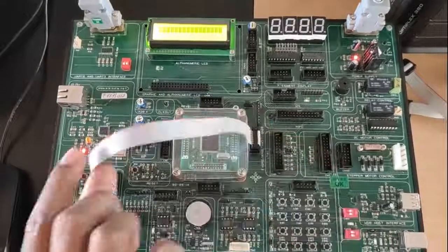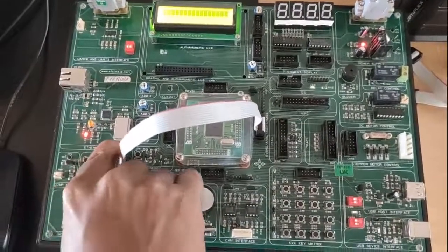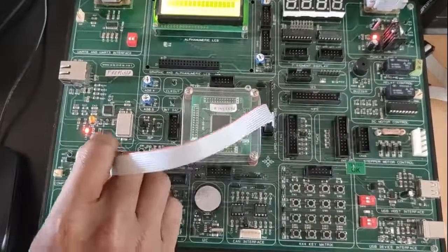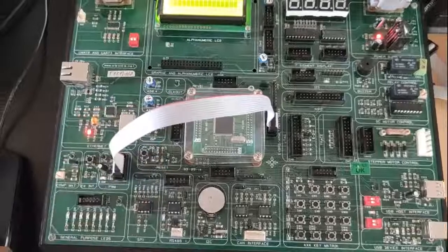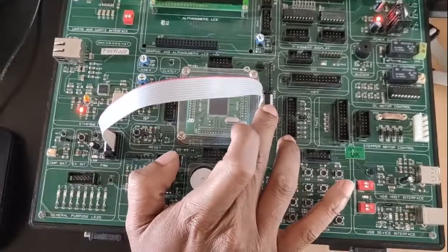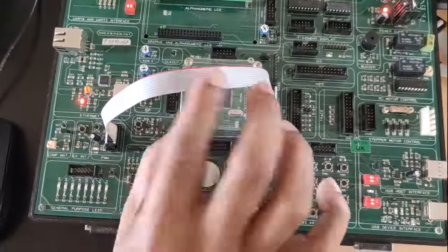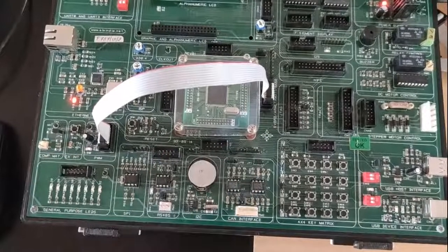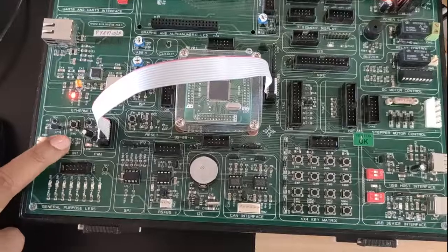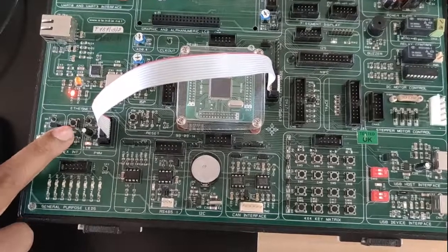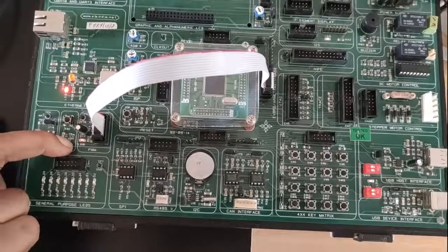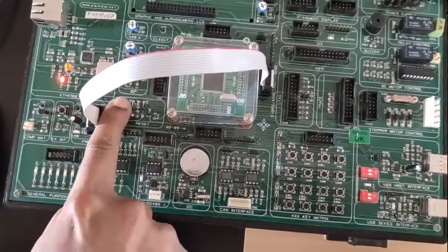Now you can observe this connection, the FRC, which is connected from CNB to CNB1, since the external interrupt belongs to port 2, which is connected to the CNB connector B. For that reason, this FRC is connected from CNB1 to CNB. Here you can observe switch 2 is the external interrupt. We have LD10, which is configured to toggle here. Now I will reset the hardware.